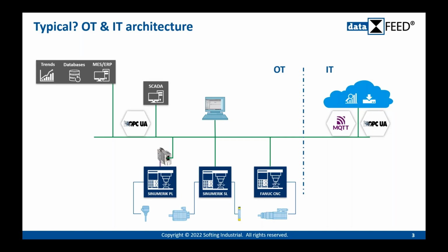But when we need to connect to trends, databases, or ERP systems, there are different providers and different solutions in the market, and it's not straightforward who is going to do this. It could be the OT side or the IT side, because in the end, all of these tools require more knowledge than is commonly found in the OT infrastructure that reaches up to the SCADA level.